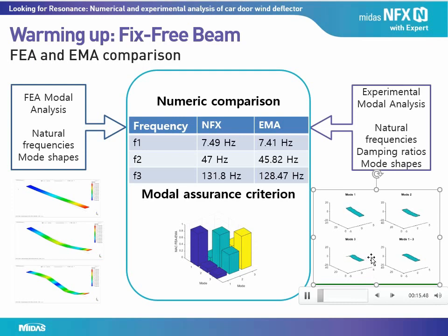Since one of the measurement locations is at a node of this mode, and we have just 4 points measured, one may think along this section the beam is stationary. This is obviously a wrong conclusion due to insufficient spatial sampling. The right bottom graph shows combined vibration.